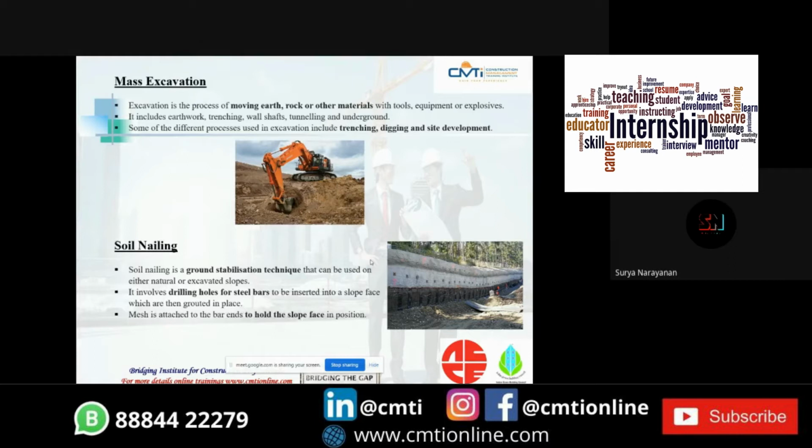It is nothing but a ground stabilization technique that can be used on either natural or excavated slopes. It involves drilling holes for steel bars to be inserted into a slope face, which are then grouted in place. The meshes are being provided, as you can see in this image. The meshes should be used for every 1.5 meters below the ground.